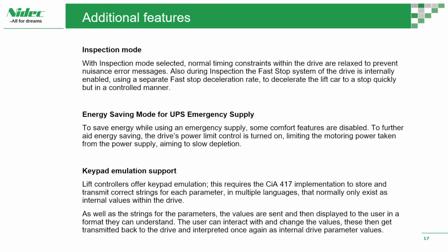We talked previously about keypad emulation. So many lift controllers support an emulated keypad. Normally, the way the drive works is that the drive internally only has its internal values, and it's actually the keypad that has the text strings, and that allows us to do translations as well.